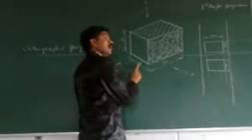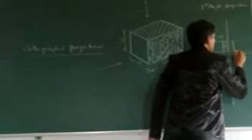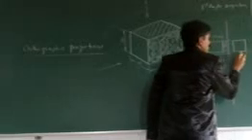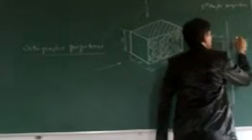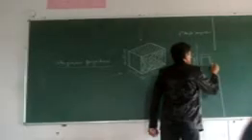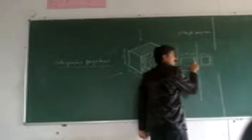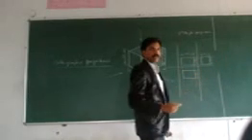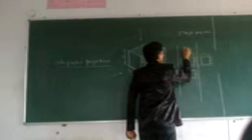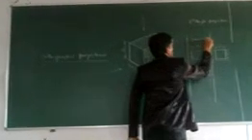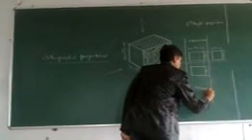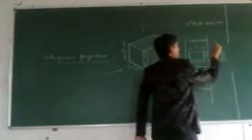And what about the width dimension? This is 50 and this is 40. So this is 50 and this dimension is 40. Actually we have shown it here, but if you want to be very particular, just show the dimensions of the side view. And simply write here, this is the front view, this is the top view, and this is the left side view.